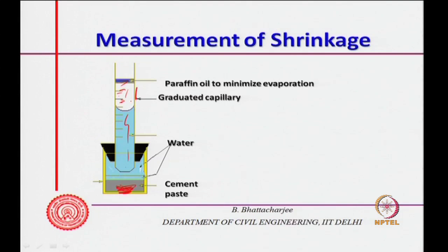So, chemical shrinkage is because of the volume change of the paste. As the volume of the paste shrinks, the water level changes; there is full water, no evaporation loss, no drying, nothing else occurring. So, as we discussed, stoichiometrically you can find out how much volume change of the product would occur. So, you can measure this chemical change. This is done in the early stage.